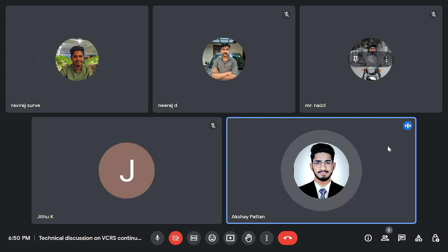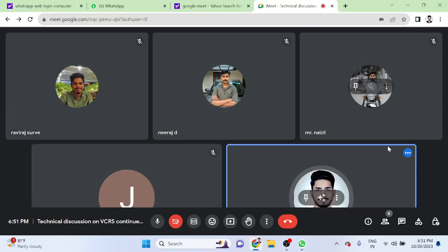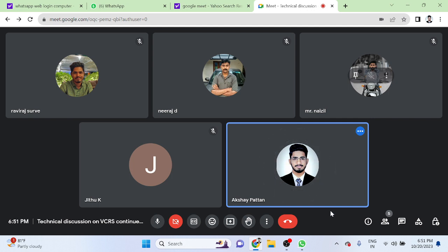So the refrigerant is obviously coming from the thermostatic expansion valve only. There only the sudden drop of pressure and temperature is happening, right? So the pressure and temperature at the thermostatic expansion valve and the evaporator coil are the same, guys. If you follow, I will just share the diagram. Just a second, I will share the diagram.